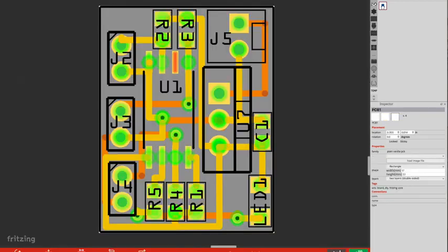The PCB then looks like that. In the middle there, you can see with these elongated terminals is the surface mount IC, complete with surface mount resistors, surface mount capacitor, whatever makes sense. I haven't done a surface mount regulator. Unless you need the height, it's probably not worth it. This comes out at 17 millimeters by 22 millimeters, which is half again of the one we've just looked at. So it just goes to show you can save a lot of space by designing your own PCB. I want now just to look at one last example.